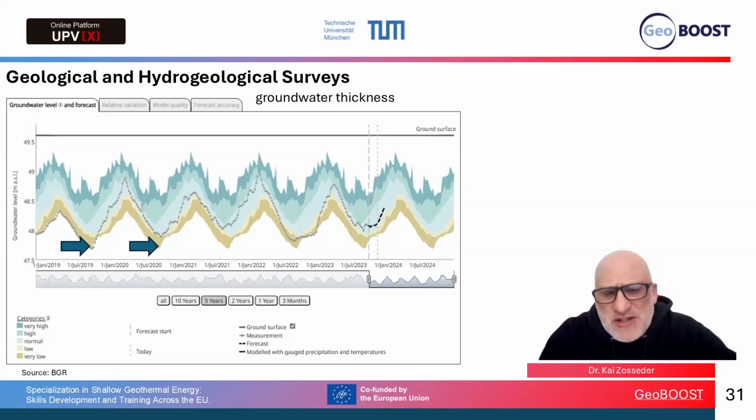You have to analyze groundwater time series for that, and also keep in mind prognoses for the future, because climate change unfortunately also changes our groundwater table. Normally, if you have enough groundwater available, it's not so sensitive, but you have to be aware of it. So if you plan with low-level groundwater tables and groundwater measurements, then you're on the safe side.